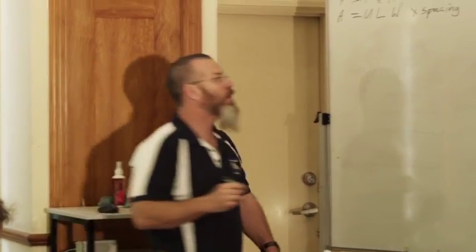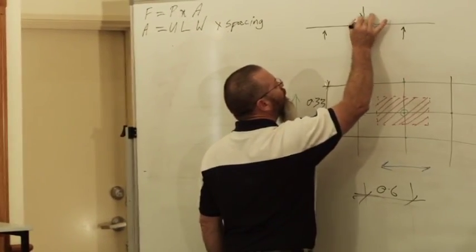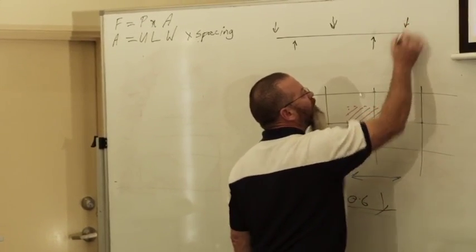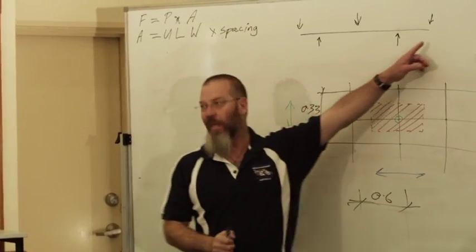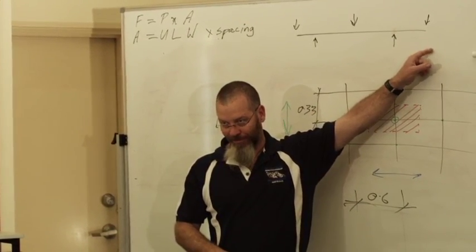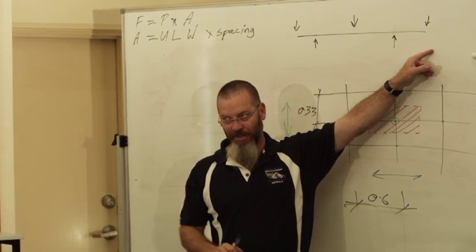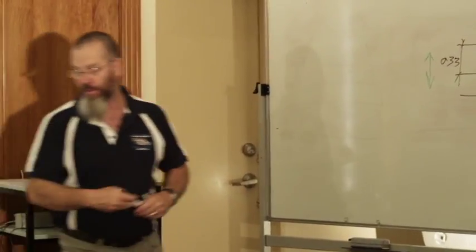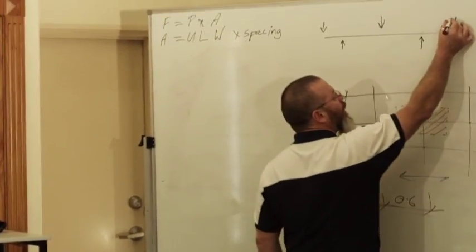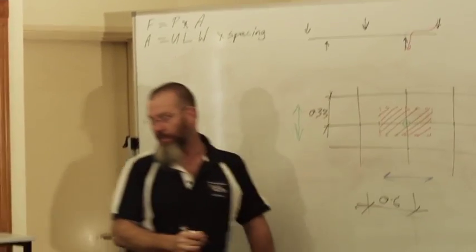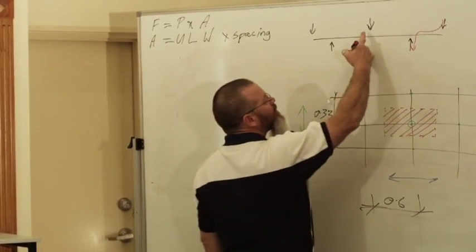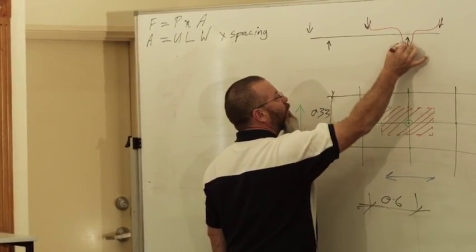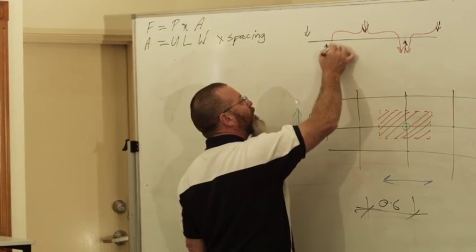That's it. I'm going to put a point load in the centre, and I'm going to put a point load here, and a point load here, just for the purpose of demonstration. If I was standing out on here, nailing the fascia on, which I'd never do, but just say I did, where would my load go? Think about the path of the load. Back down here, isn't it? Yeah? And then, I don't know, if I was standing in the centre here, where would my load go? Half the load would go this way, and half the load would go this way. Same here.